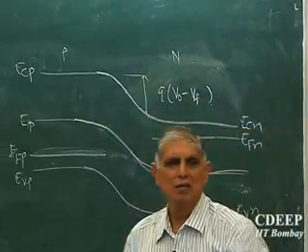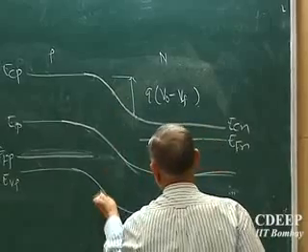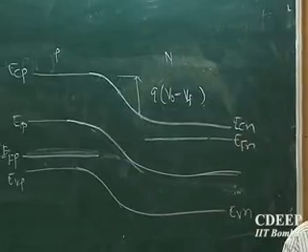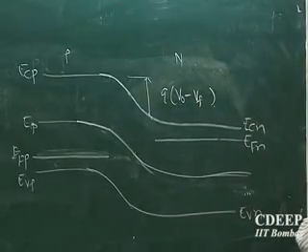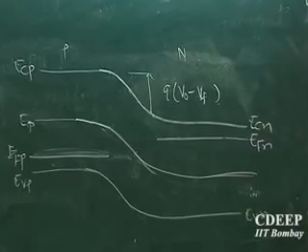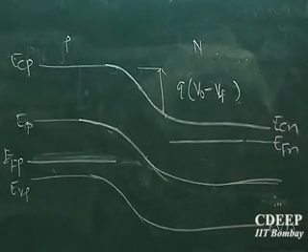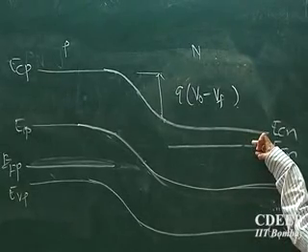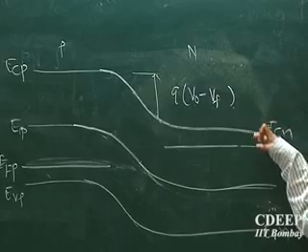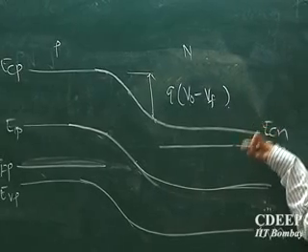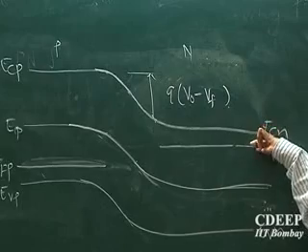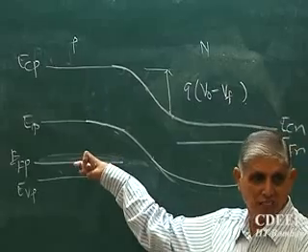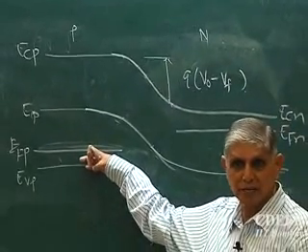So what has happened? These are parallel. Since you say it is V0 minus Vf, the conduction band of the n side went up. Fermi level corresponds to what in steady state, or in Boltzmann statistics? This is related to the EC position. Is that clear? So if n has to go up, this must move upwards. Is that correct? But P we haven't changed, so P remains separated as it was.